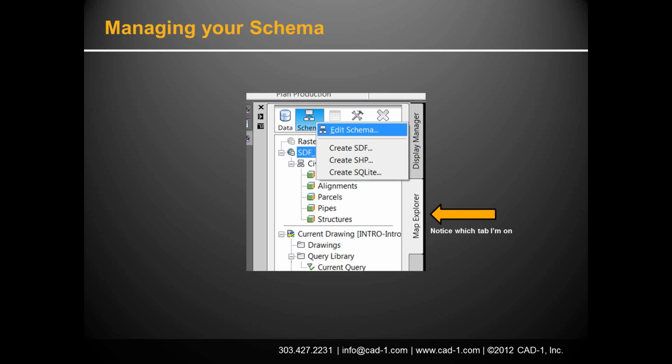Okay, so you saw editing the schema. That's how you're going to build on your GIS. Throwing the drawing objects in there is relatively straightforward, especially since I can keep appending to it. So I've got 15 projects, but they're in 15 different drawings. I don't want to have to combine them and so on. Don't worry about it. Open them one at a time, throw them into the same SDF, keep appending, keep appending.